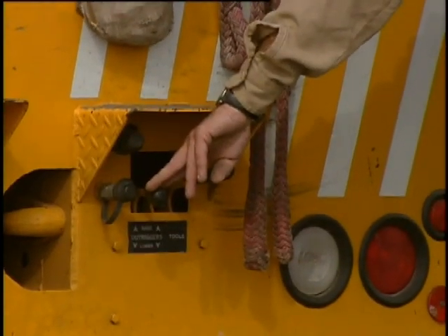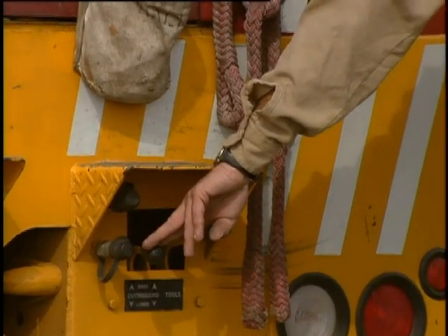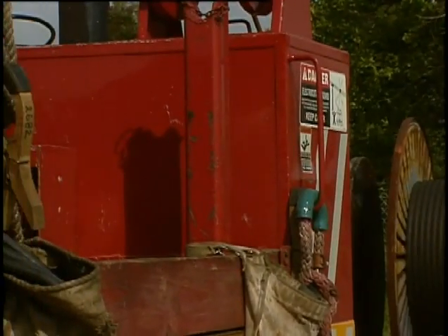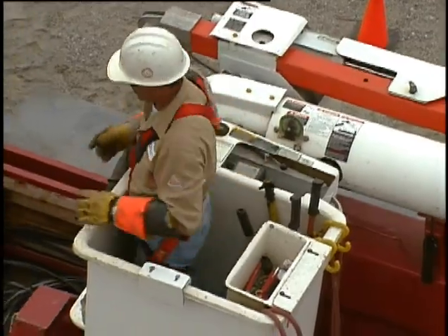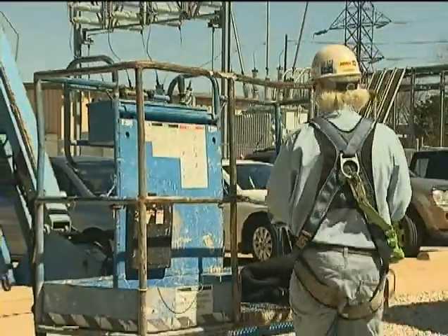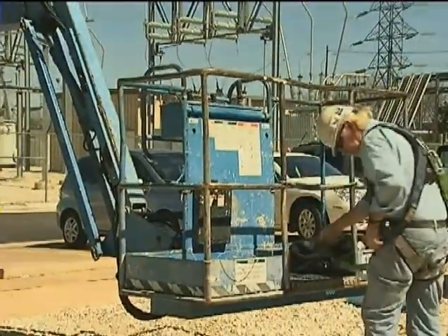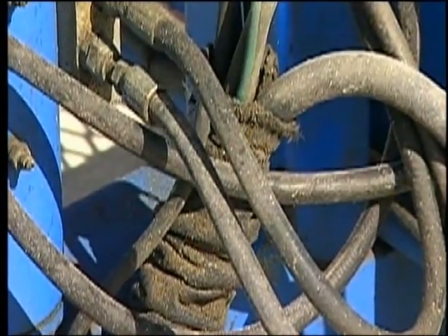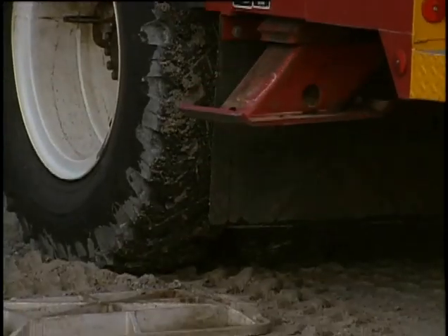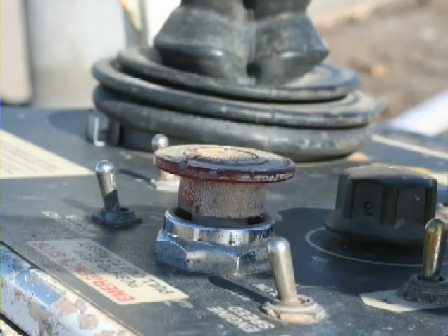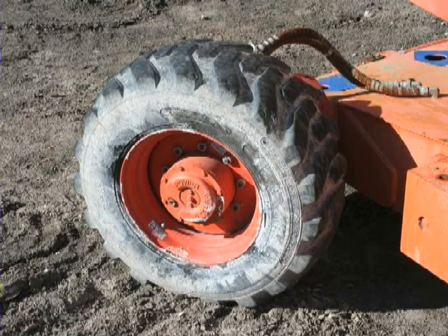Controls should never be forced from one position to another. Always inspect the boom for damage and/or any signs of weakness. If the lift is insulated, make sure it is dry and free of grease or oil. Check the guardrails. They should be free of damage and at the proper heights. Check the hydraulic system for possible leaks and the fluid level for proper amount of fluid. Outriggers should work properly and should always be set. Emergency stop buttons should work correctly. Tires must be properly inflated and inspected for damage.